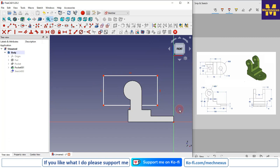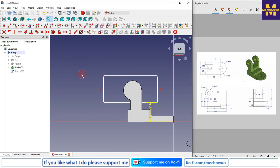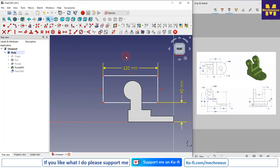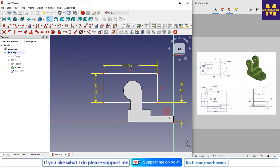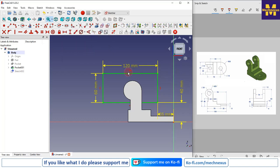Now I will select my origin point and this point and give my vertical dimension 40, and we will give some approximate dimensions to constrain our rectangle, 120 by 60, and let's say 35.